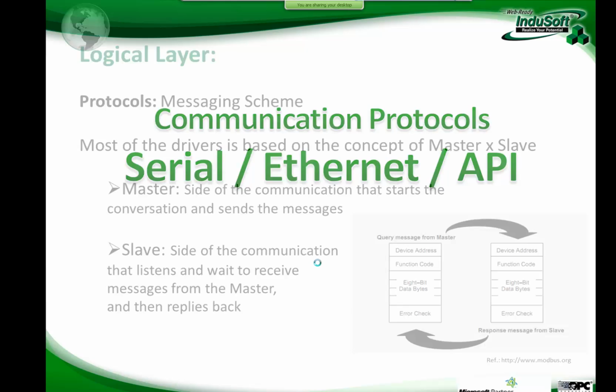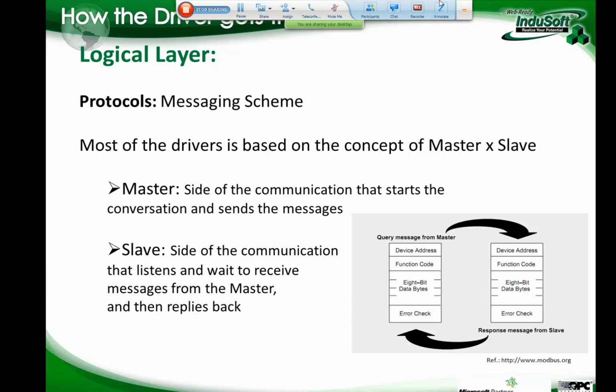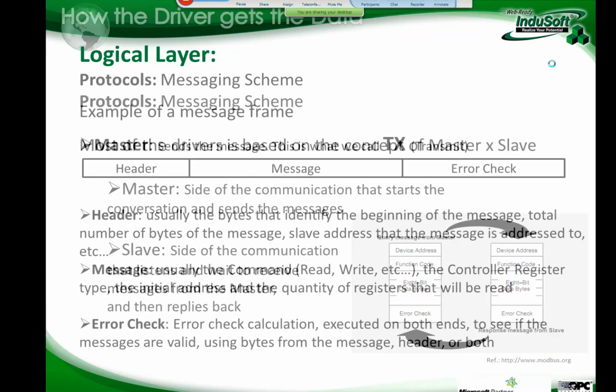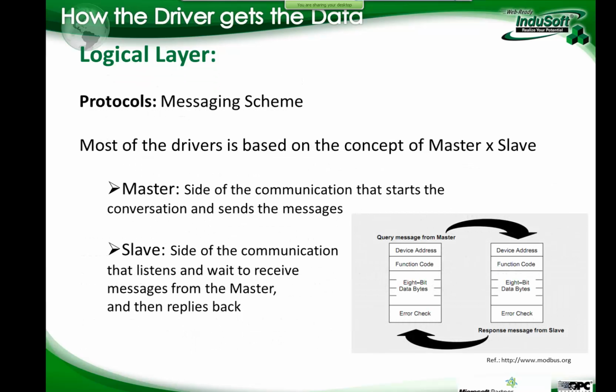So, a little bit about the next topic. Once we have connected the PLC, how am I going to exchange information with the PLC? How is the data exchange going to work? That's when you talk about the logical layer. The word protocol here means exactly what bytes I'm going to send to the PLC and how the PLC is going to respond to me.